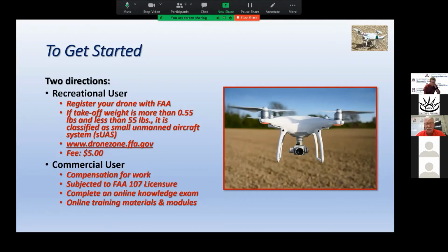As I started looking into flying drones and investigating getting my FAA licensure, I was looking at just where I could actually fly it here near the University of Arizona. I know where our farm is located, we are a certain distance from the Tucson airport, but we would still be in a certain class airspace. And if you're going to fly in class C, B airspace, which is within 5 miles of an airport, under regulations you must apply for a waiver to be able to operate in that airspace. That's so we reduce the issues or incidents of interference with manned aircraft traffic.